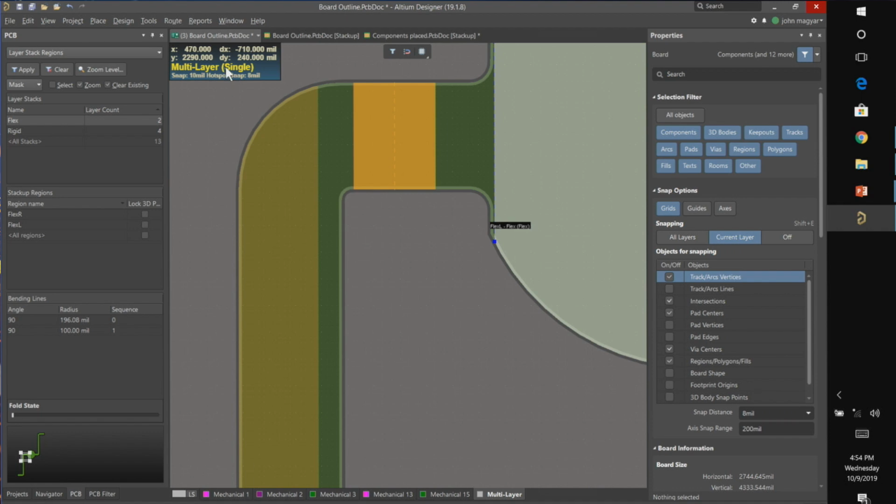I think it might even be in the component definition, but you can add it. It's its own object, and it'll have dimensions, so it'll be a cavity, and you give it a start layer, a stop layer. And I had a great example, but you can have them top facing or bottom facing. So that's another thing in the stack up.